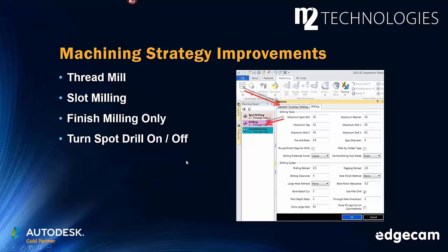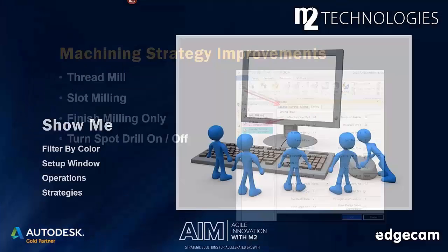And they should do a great job of being a toolpath accelerator that quickly builds the toolpath for common part features, where you can just confirm, is it the tool you want, switch to a different tool if needed, change a couple cutting parameters, and move on to the next thing in the list. We also suggest looking at them as the idea of what could happen if you were to refine those to better suit your company's specific machining requirements, so that when there's, say, a hole in your part, or you've got a rough turn and then rough bore your part, it's kind of the same process all the time. Just do it our way. That's how those are done for the machining strategies.